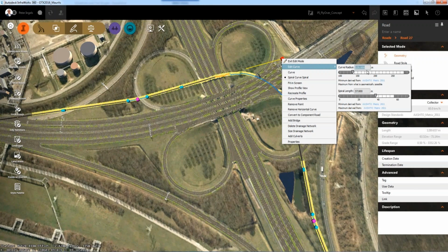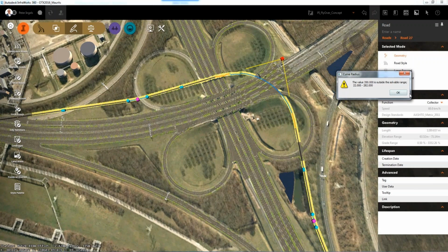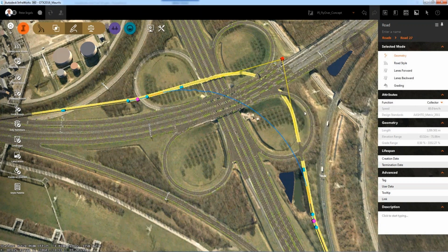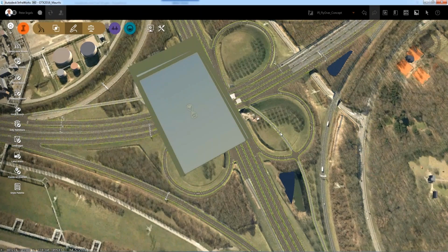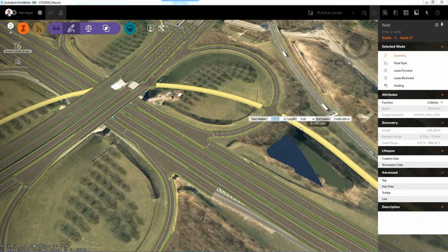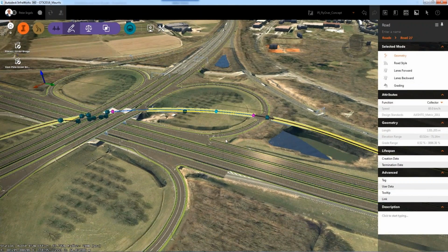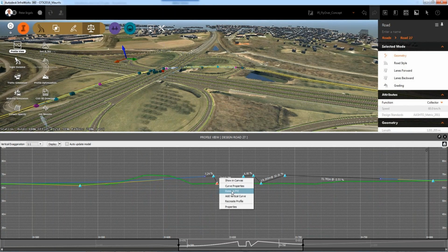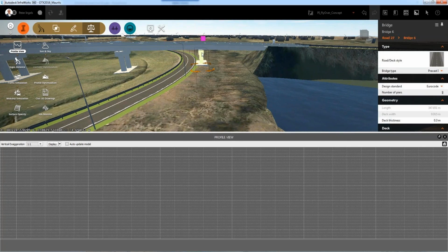And then based on this real 3D data, you can start to design the concept of the bridge. But concept of the bridge for us also means to add geometry. So you have to know, or you want to design, what the radiuses are, what, for example, the superelevation of the bridge is, and you will see now I will specify, okay, my bridge will go through some points, so I will define how the bridge will look like, where it starts, where it's finishing.